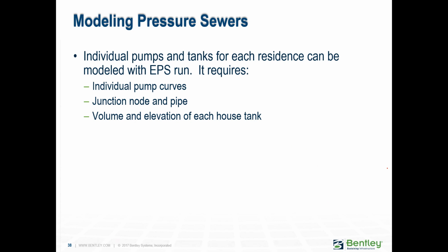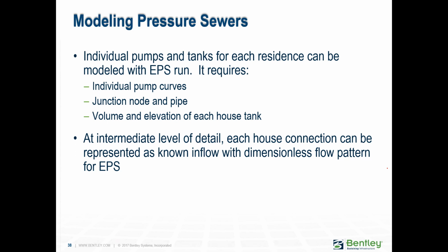Okay, so you decided that you are going to go with this. How do you model it? You can, at each residence, draw an individual pump and a tank, and then enter the individual pump curve, the elevations, the volumes, and that could be okay if you have 5, 10, 15 houses, but if you have 200 houses, it's a lot to input and to work.